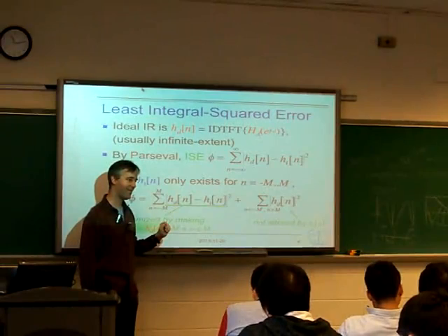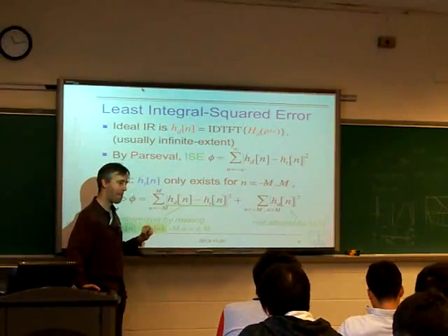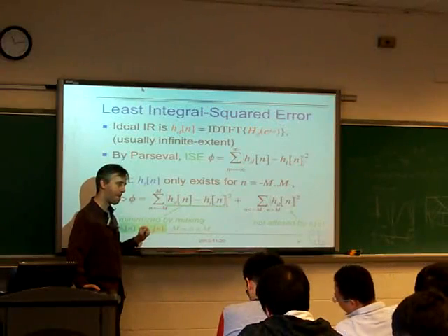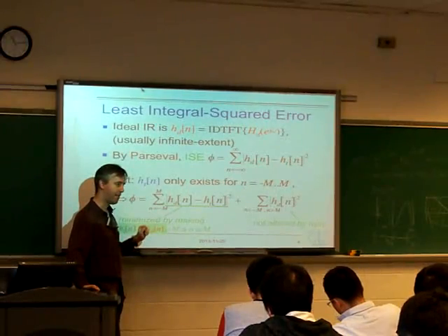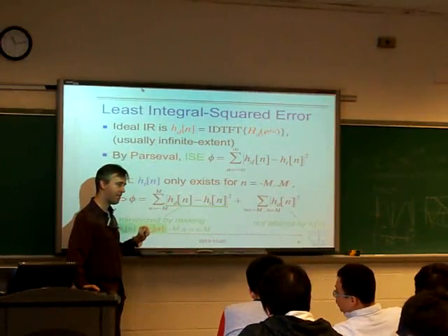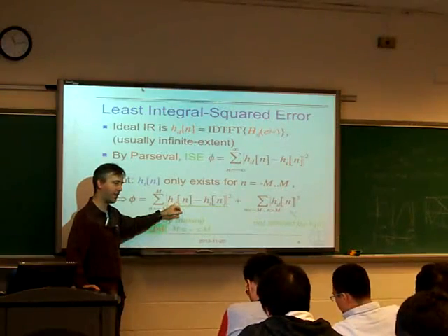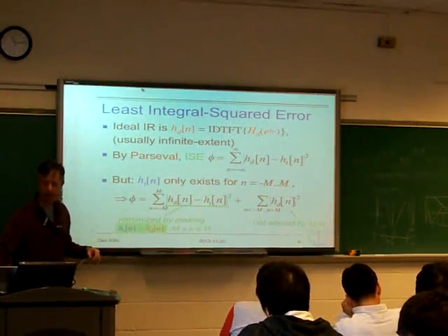Say the coefficients for that FIR filter, if you're taking an n-point FIR filter, those n coefficients of ht of n. So how do we get those coefficients first? We just take hd of n and take those values from hd of n. Let me show you the next slide.